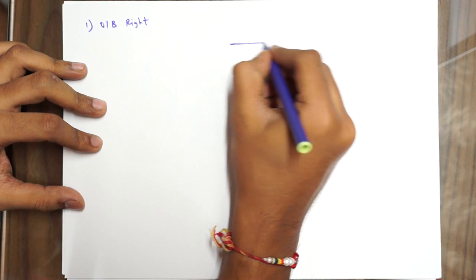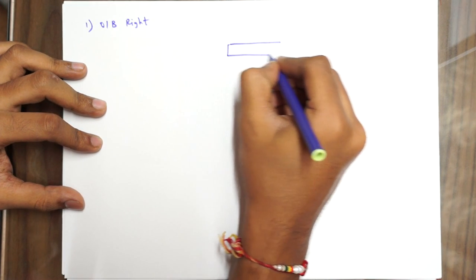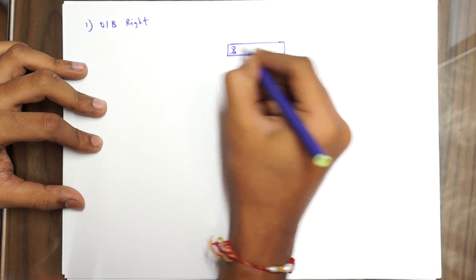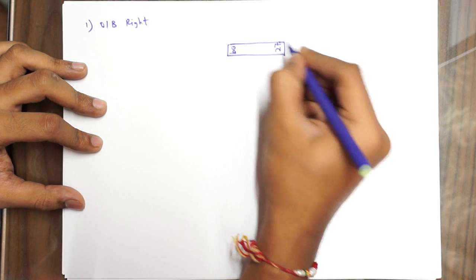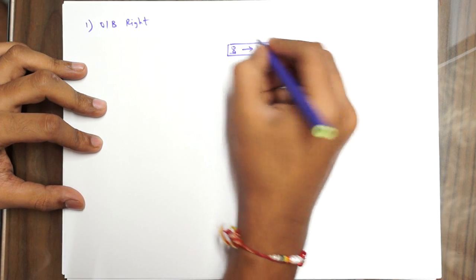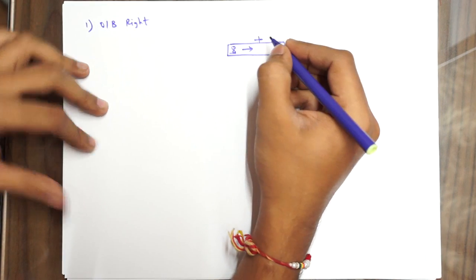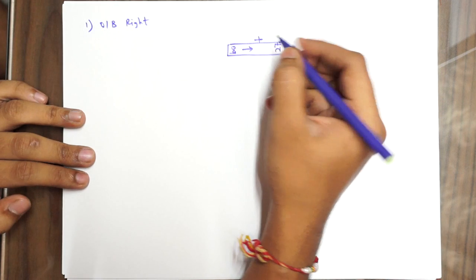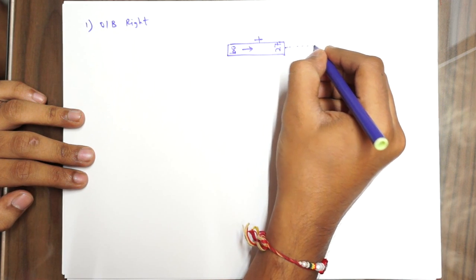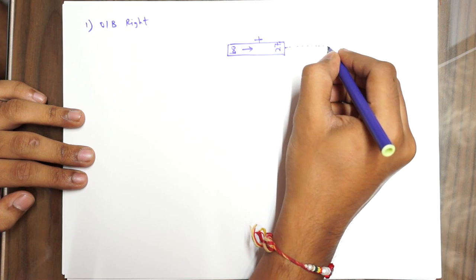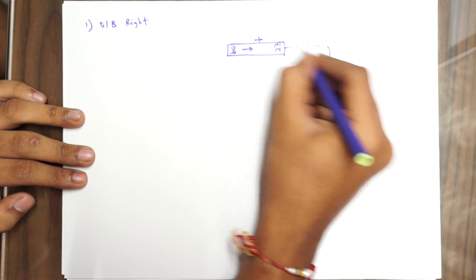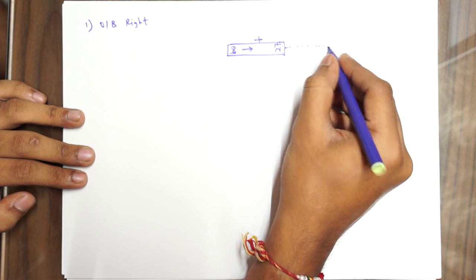Now I'll start with a runway. I will just take a standard 09 and 27. Imagine you are on the runway here, and this VOR is apparently on the runway itself, just for understanding purposes, and you have been told to establish a 5 DME arc. That will be something like this. The distance from this VOR is 5 DME at all points.